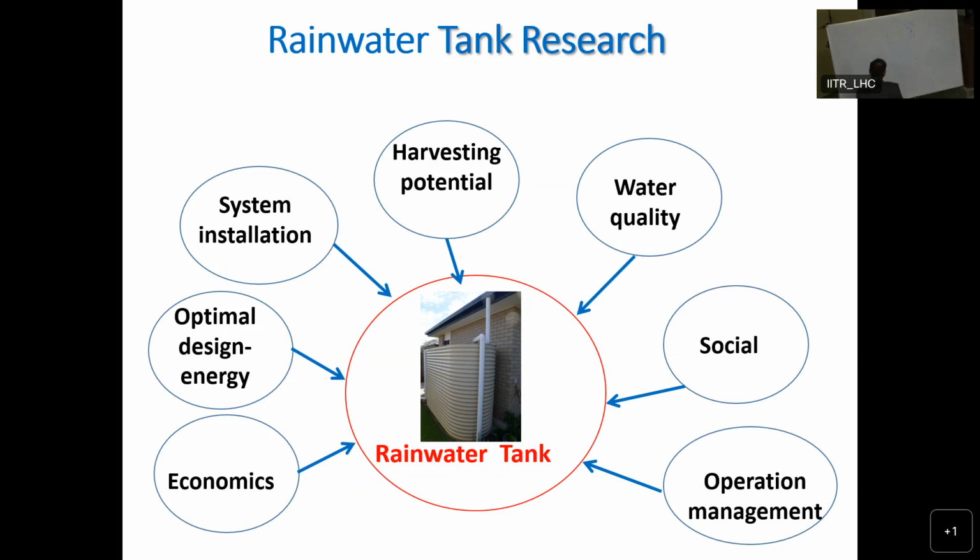So we consider that for 112 days there won't be any rainfall. Then there are 4 persons in a house, and we are providing how much water for each? 150? 135? 100? So that will give you the size of the tank.